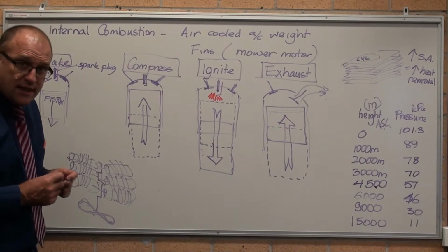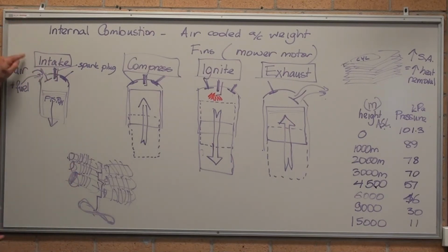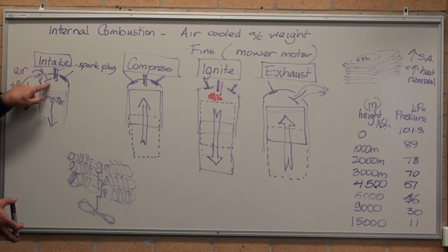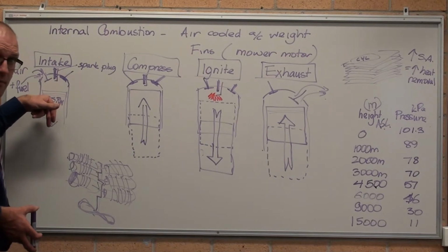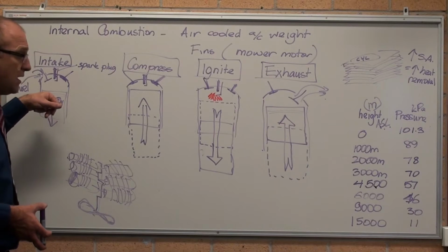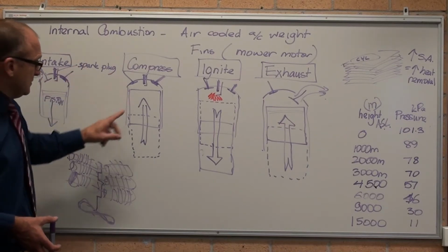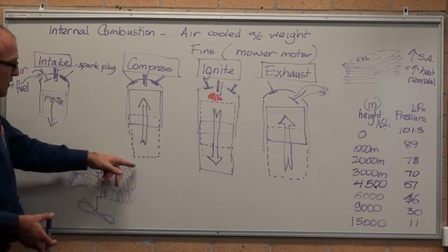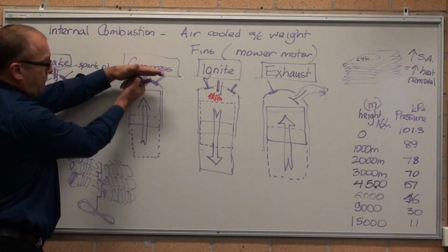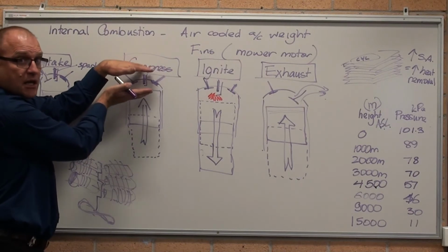4 stages in the internal combustion engine. There's 3 things: intake valves, exhaust valves, and a spark plug in an engine. First stage, the intake valve opens, the air and the fuel mixture gets sucked in. The fuel is vaporised in a carburettor or a fuel injector, depending. The piston travels down. When it's down, second stroke, piston pushes up, compresses the gas, as we said, increased pressure,